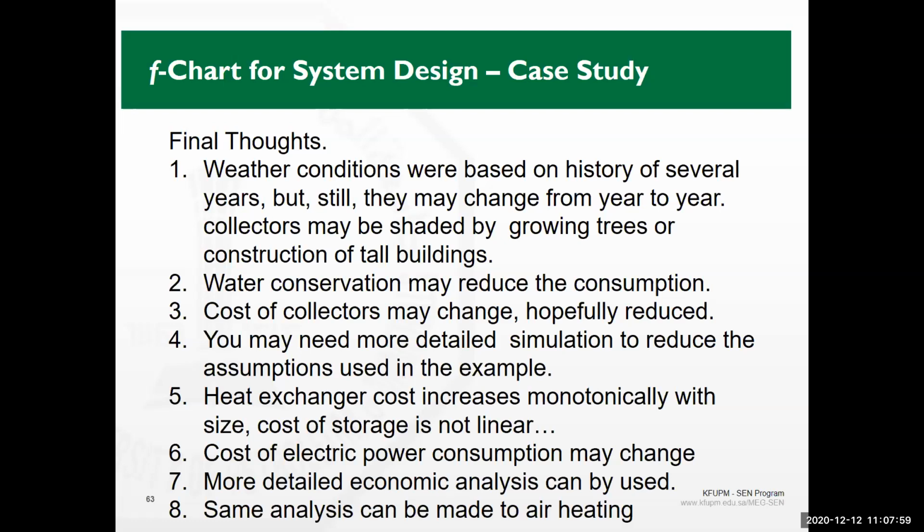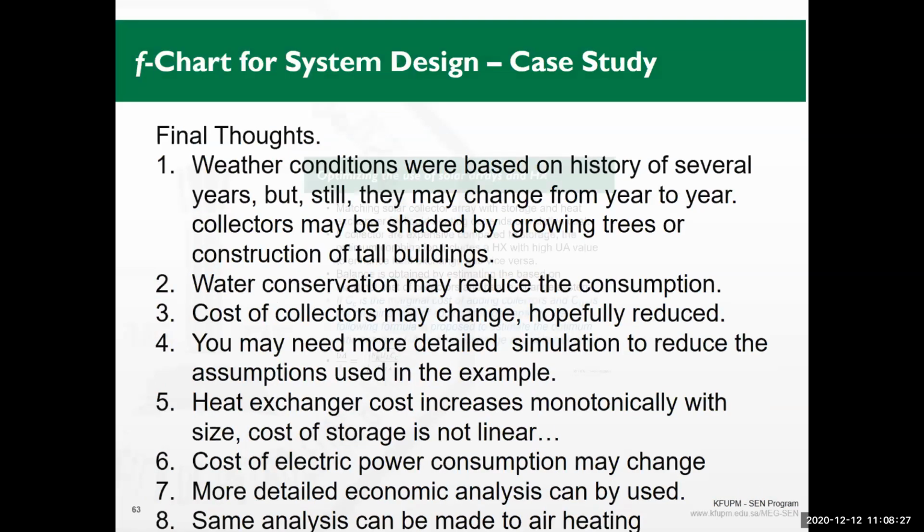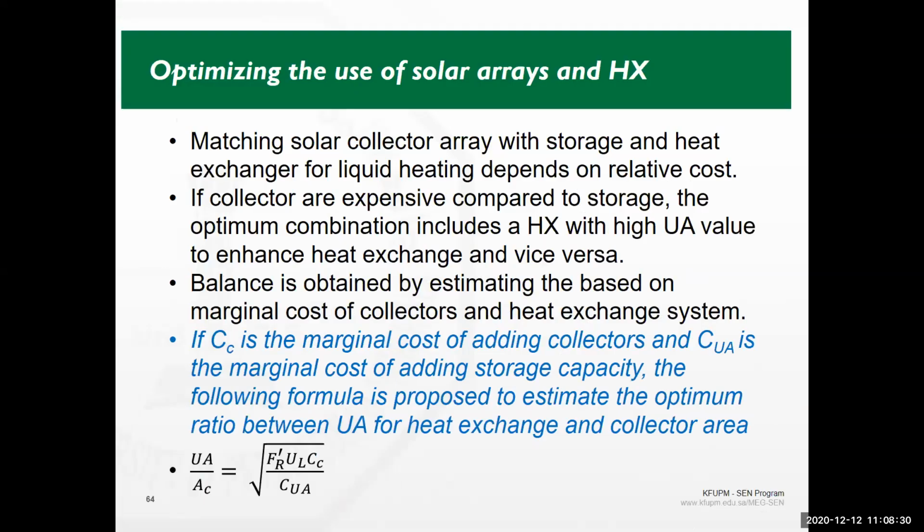And if you need to do air heating, you are going to follow the same procedure that we have done. Probably changing the F equation is going to be the major change that you're going to have here. Definitely, talking about the MCP delta P, we are going to talk about how much will be the flow rate of the air. The CP value of the air is quite different from the water, and what is the temperature you're expecting from an air system. But that would basically be for space heating, not for just hot water cooling or heating like that.